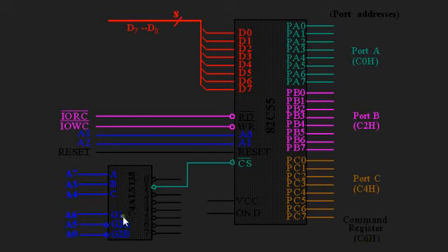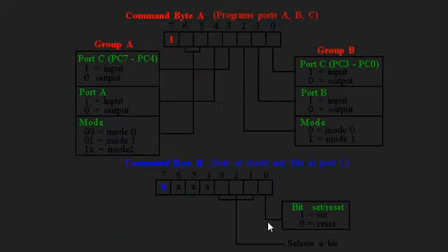Now here we have a control select which is connected with some address ports. Those generate a control signal which is CH and active low, and here it is connected with reset, address, read and write, active low, and the data section which is from D0 to D7. In the bottom we have VCC and the ground. This is the port address section diagram. Now moving to the next.